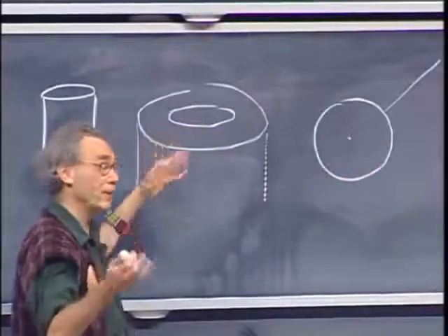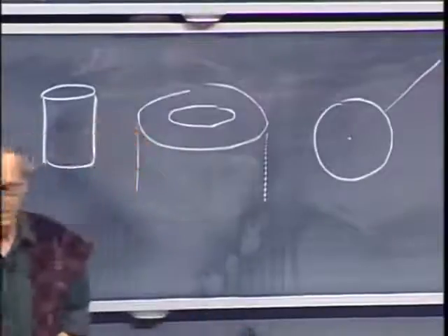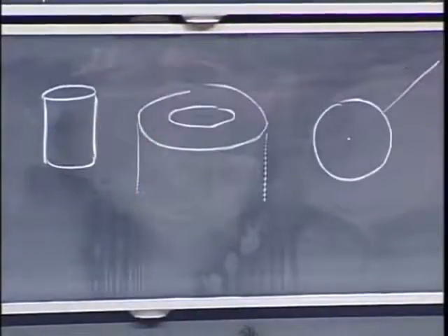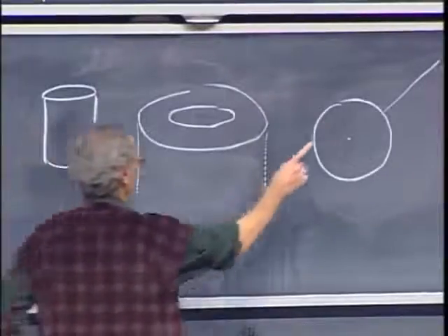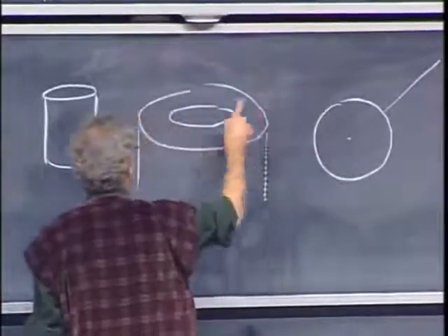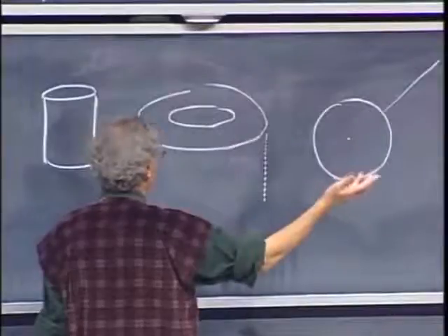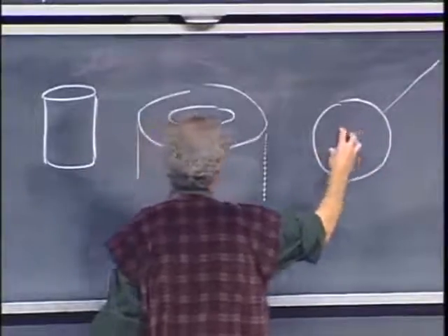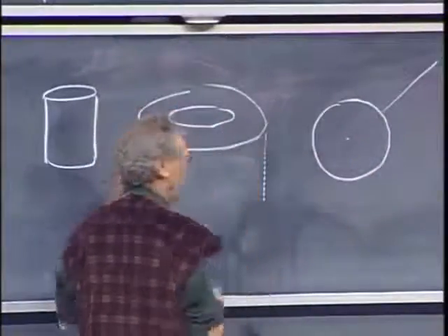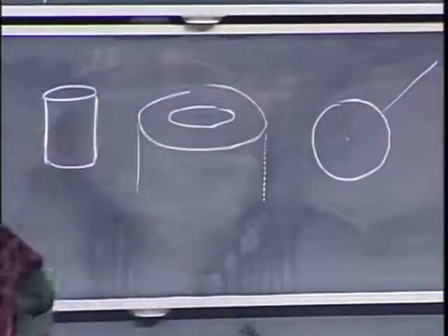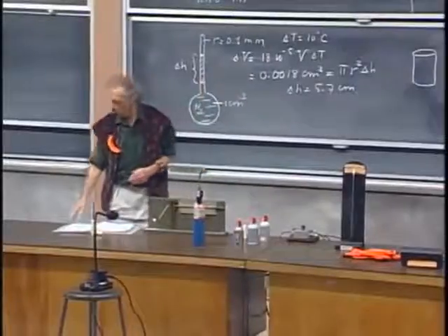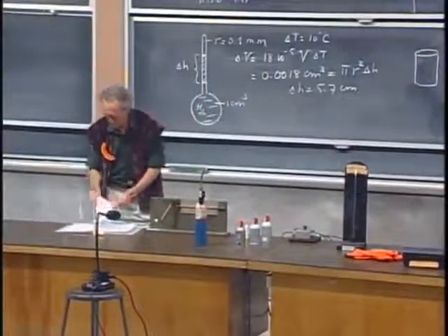So it's the reverse, but at least you get the idea. And then if you wait, and it cools, when you bring them in contact with each other, this one will cool, and this one will get warmer. So you catch two birds with one stone. This one will shrink, and at the same time, this one will become a little larger, and so then clearly it will fall through. And that's the idea.